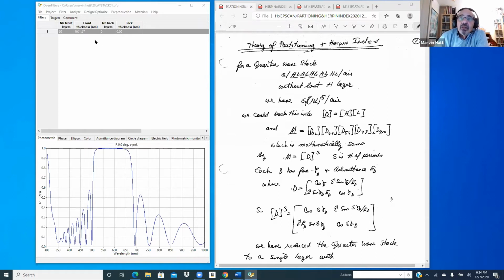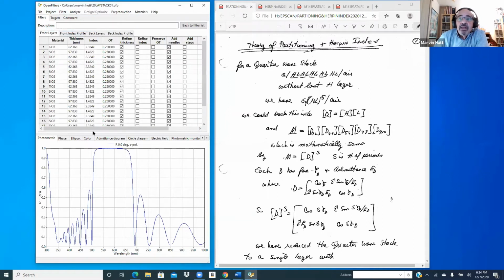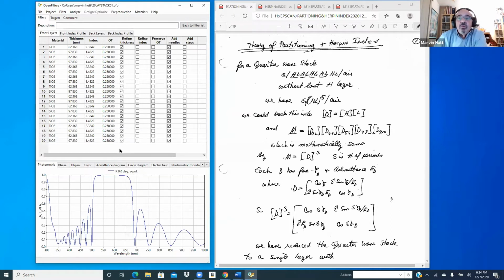Now, over on the left, I have a filter project. Let's modify the filter. Now this is the reflectance of the stack. Here is a quarter wave stack, and it's made of two materials. Notice that all of these are quarter wave, and it's high, low. This is modified. High, low, stack 01. Did I make the stack 01? Yeah. Okay. No, it's all quarter waves. That's correct.